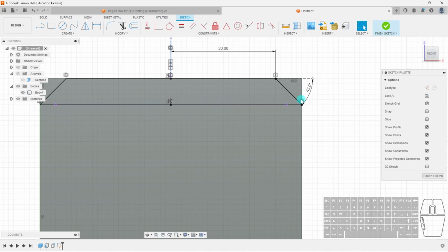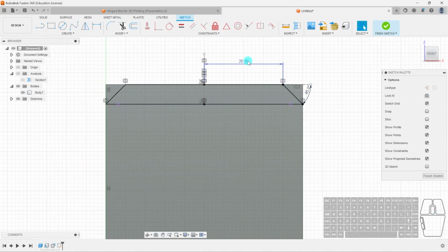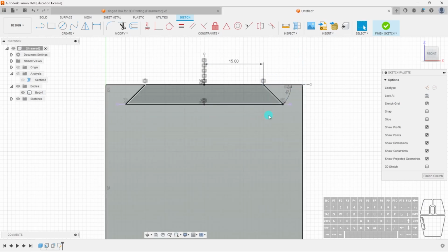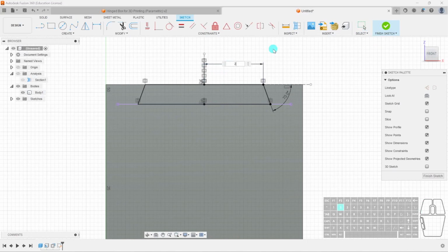But of course now it's going to cut out. What do? Easy. I have this dimension as well. I can go back here and bring it back to 15, you see? So just like that, I can always make easy changes to my sketches as long as I drew them correctly the first time. That's why it's important to dimension your sketches and make sure they're fully constrained. In this case, maybe 45 degree might be a little bit too much. I'll just do 70. That looks fine. And again, see how easy it is to change things. I can always go back to 20, and that's fine as well.